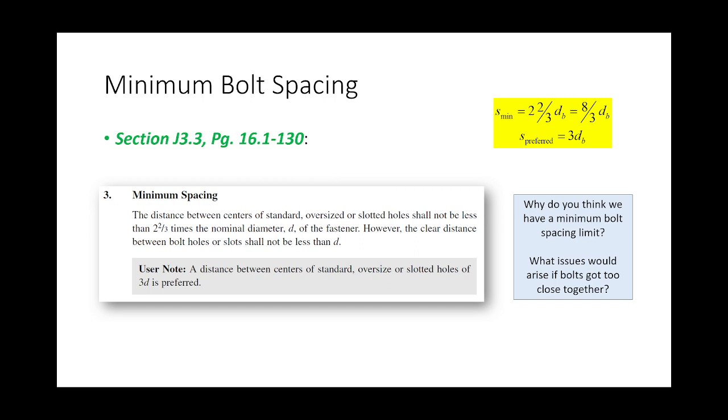So it has nothing to do with strength. Again, now what you were saying is, you were saying that there needs to be enough material to resist the load. That is true. I'm not saying that it isn't. This is why what I said earlier, I said that just because you meet bolt spacing limits doesn't mean you don't need to check bolt bearing. You still need to do it. They are separate issues altogether.